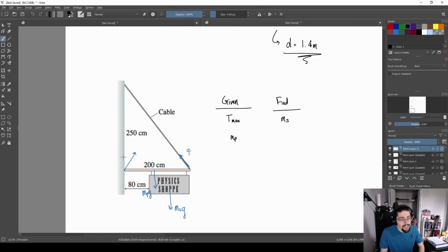So if we were forced to pick a pivot point, we need to say, we know this thing isn't rotating, but we need to look at one place where it feasibly could be rotating around. The spot that I'm going to pick is the one that makes the problem as easy to solve as possible. And in this problem, that's right at this spot. My pivot point is there. Now, the torque from my mystery force, 0. It doesn't matter. It doesn't show up in the problem anymore. I'm done with it. We don't need to worry about that force anymore.